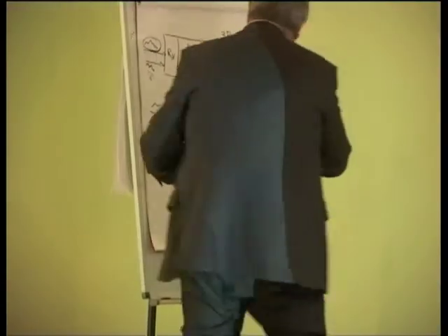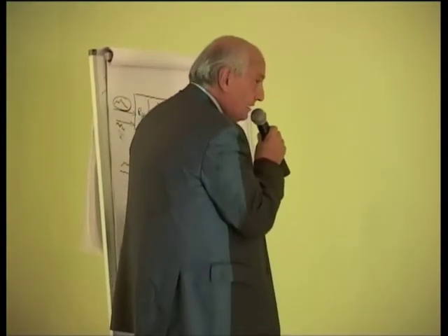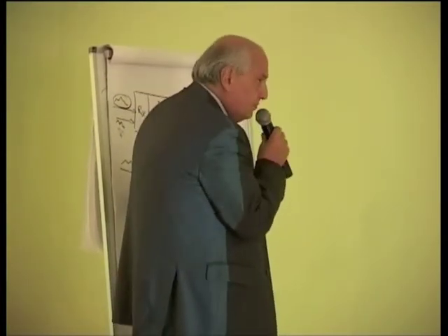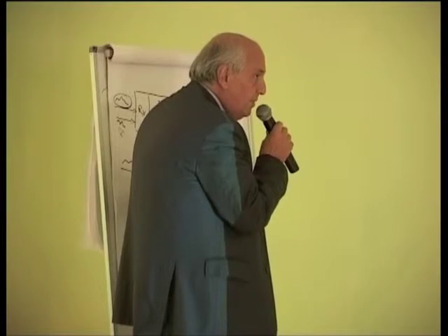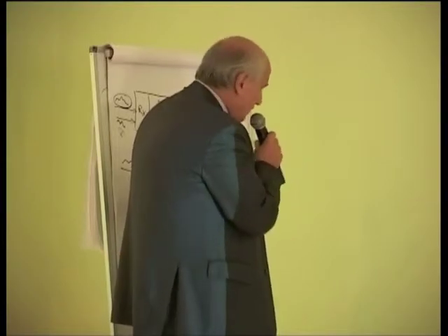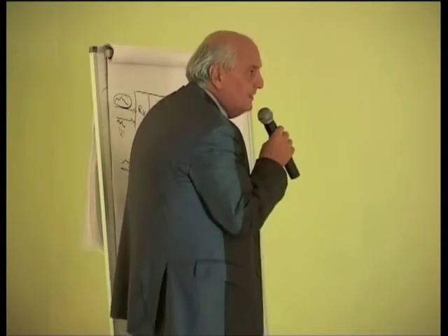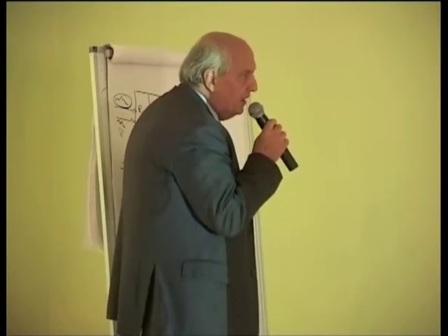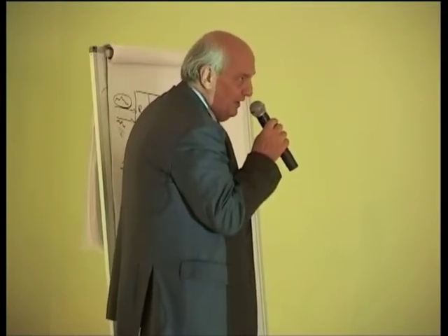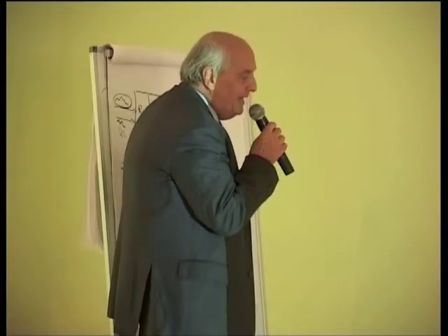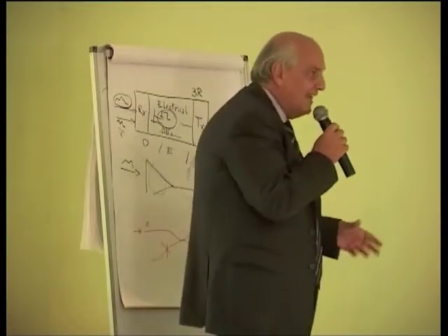It's very simple. As I have shown you in this very simple example, if I divide the power into branches, on each branch I have a loss of 3 dB. It is a theoretical loss. To this loss I have to add the insertion loss of the splitter, which is due to the fact that the splitter is not a perfect component. When you make it, you make some mistakes and the attenuation will increase.